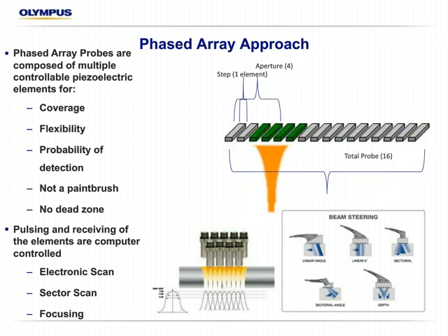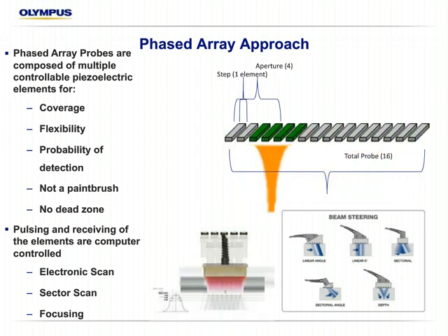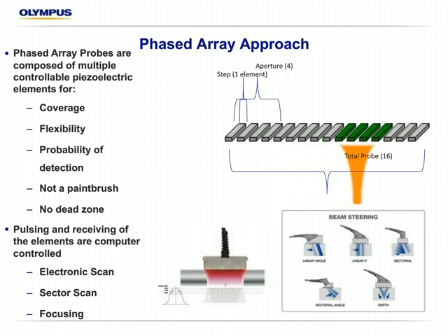With phased array, you can see all the beams are overlapping, so we don't necessarily have any dead zone whatsoever, and actually we have many overlapping beams as shown here, so we get a high resolution, or what we're going to call high data density amount of data back to that transducer very rapidly.